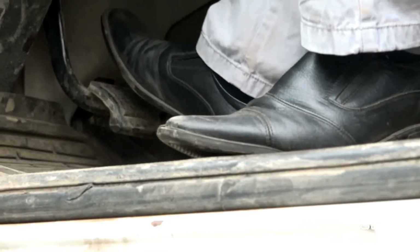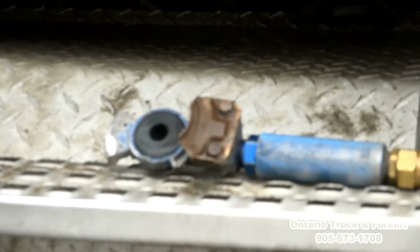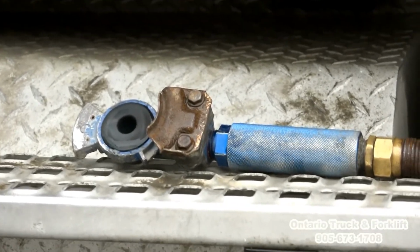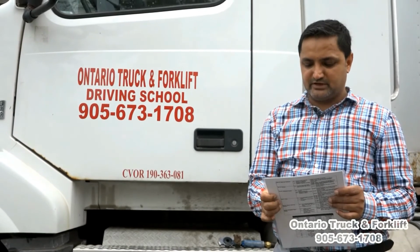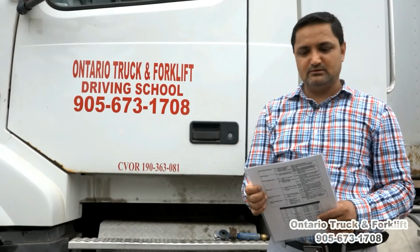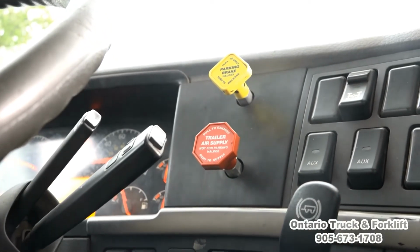Now we will press the brake pedal and listen for any air leak in the service line. No air leak in the service line means the tractor protection valve is working properly. If there's a leak, the protection valve is defective. Inoperative towing vehicle tractor protection system is a major defect. If we have a major defect in our vehicle, we have to write it in the logbook, call our owner, and we cannot drive the truck.